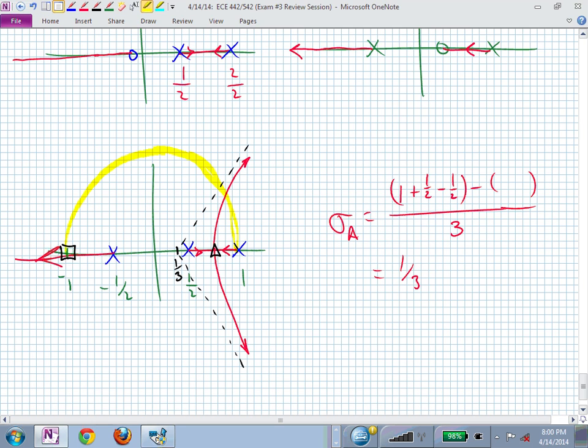Okay, the insight is before you even meet at that triangle, your one on the negative left half plane is going unstable. So you can't crank up your gain more than 1. Does that make sense? So you would say k equals 0 to 1 would be your range of stability.